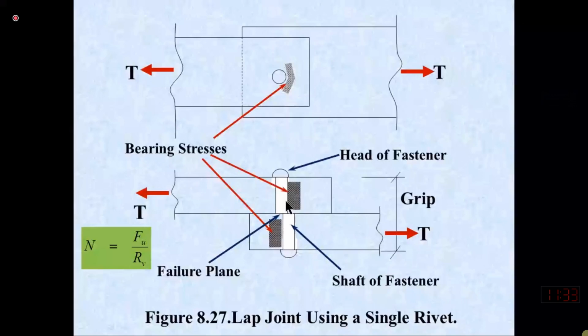So the bolt may be arbitrarily tightened, called a snug tight bolt, which we have already discussed, or we may have a high tension bolt. High tension bolt means that we are providing pre-tensioning to the bolt by tightening. The distance between the two heads after placement of the fasteners is called grip, just like I have mentioned over here.